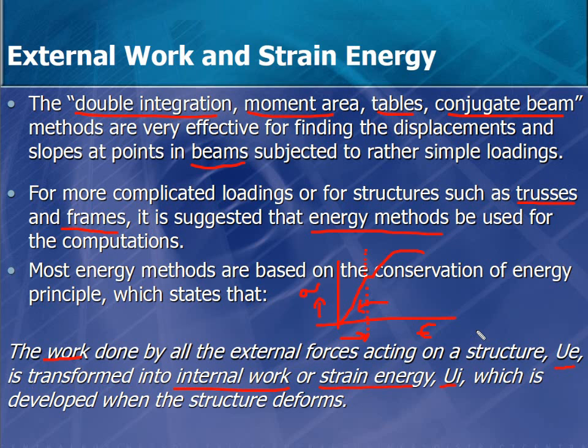Now when we say internal work here, this internal work can be due to normal force, or due to shear, which is negligible, so we're not going to talk about shear. So the internal work that we have is mainly due to the normal force and due to moment. So we have two internal forces that we're covering that will affect deflection. Shear also has its own effect on the deflection, but it's very little, so it's negligible. That's why we're not discussing it in the energy method. So we're mainly talking about normal force and moments.